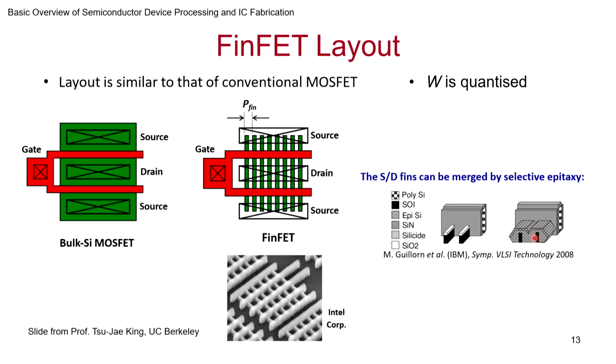So you actually epitaxially grow this. So this is the power of modern processing, and it's amazing how they do it reproducibly over millions and millions, actually billions of transistors today on a single chip, and there are billions of chips that are made. Okay, so this is mainly for improving the source drain contact. So this is how it will look. You won't be able to actually see the fin at all. You'll be able to see something like this.